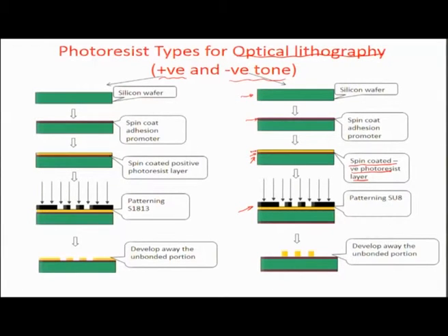The selectivity is carried out through this mask, which you can see here is the black layer where there are white openings in between and dark regions where light won't go through. So typically when we use this as a mask on the surface that we are trying to pattern, light would only go through those areas which have these open vias, and it would fall on the resist. Wherever the light falls on a negative tone resist, it cross bonds. Okay, so you can remove the remaining.